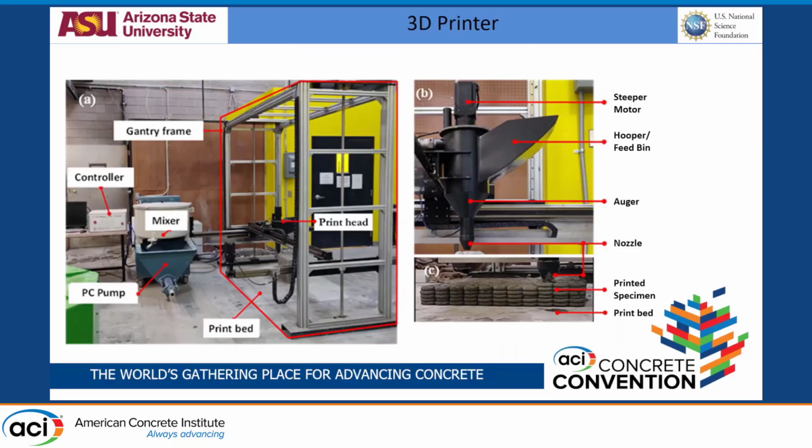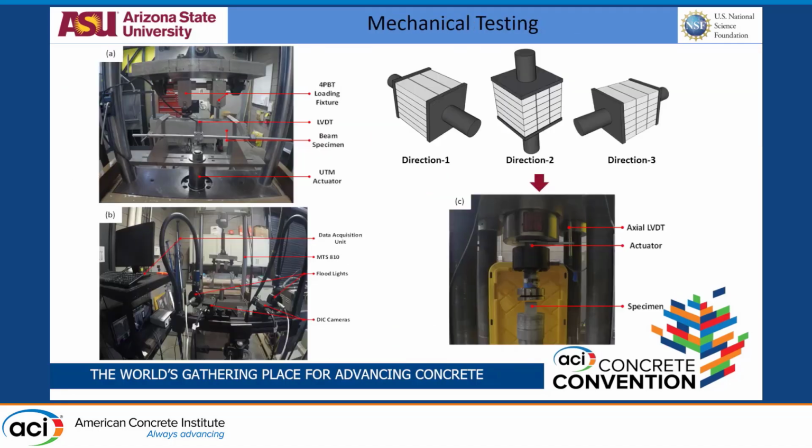And we printed large specimens like the ones you see here. We then cut out cube samples and beam specimens out of them. The beams were tested in D1 direction only. In the D2 direction, again, there will be an interfilament kind of strength that comes in. So we are looking more at a linear filament, where we look at the strength in the print direction, but we wanted to look at anisotropy also, because the build-up direction will be important in prints, because that's the direction you'll usually have loading in.